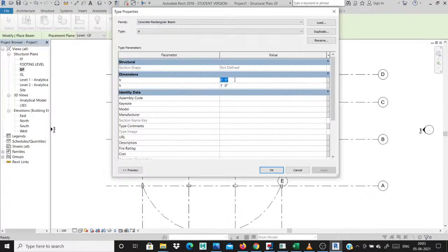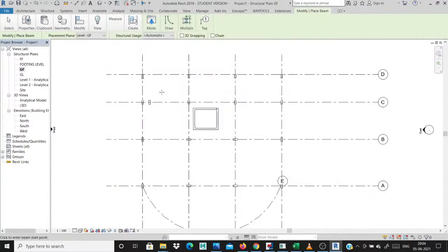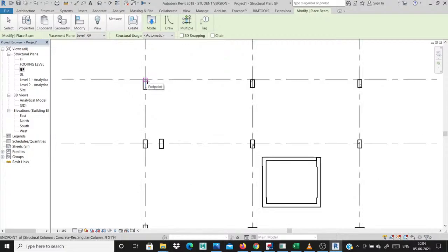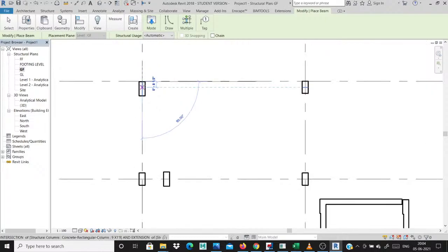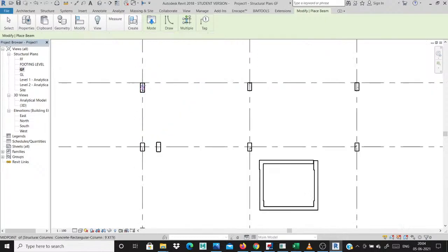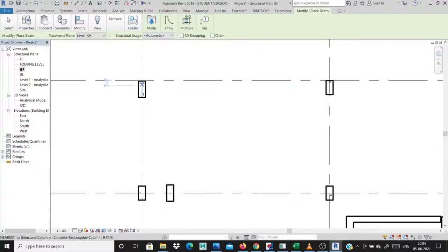Okay, my beam width is 9 inch, my beam height is 1 feet 6 inches. I click this 1 feet 6 inches. I created these grade beams also in this portion. See, there are some portions inside also. So you take this to your center portion, then it will be created. The eccentric footing is too difficult, this portion and this portion. See this, I created this.